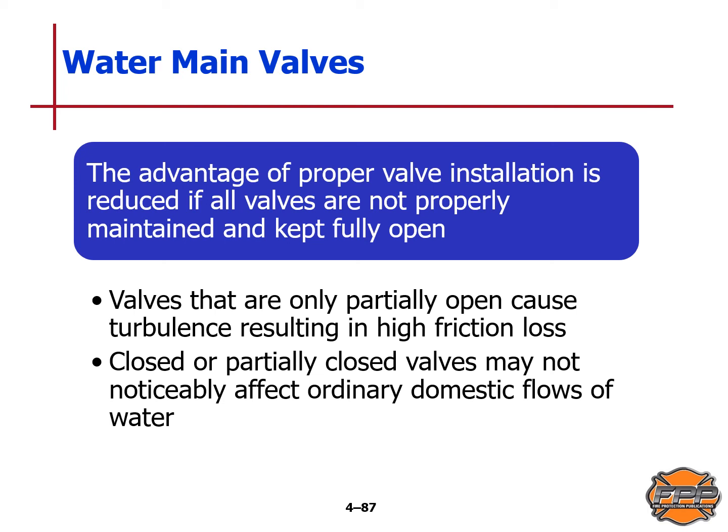If valves are installed according to established standards, only one or perhaps two fire hydrants will have to be closed off from service while a single break is being repaired. The advantage of proper valve installation is reduced if all valves are not properly maintained and kept fully open. Valves that are only partially open cause turbulence, resulting in high friction loss.